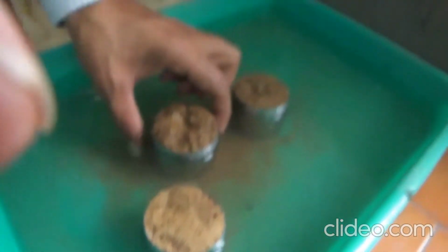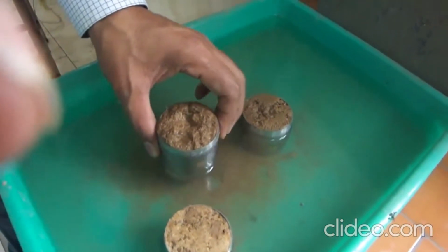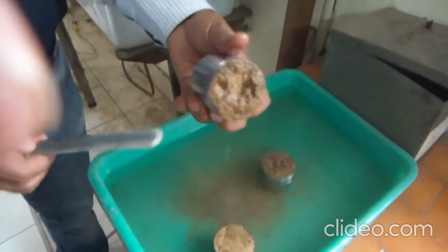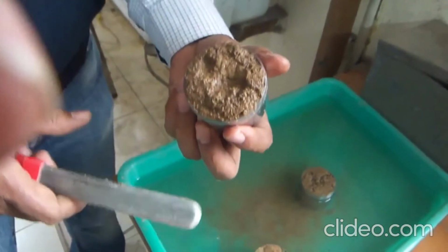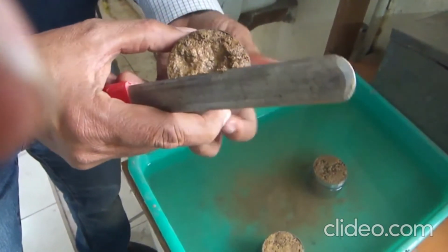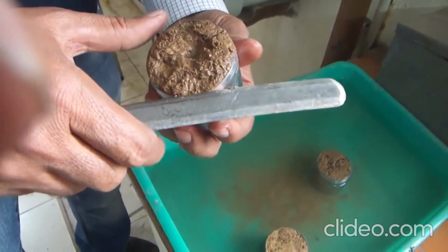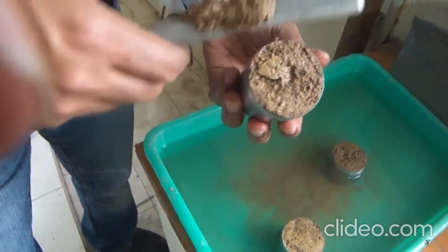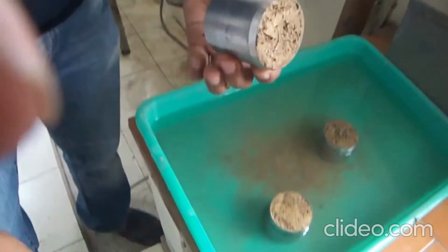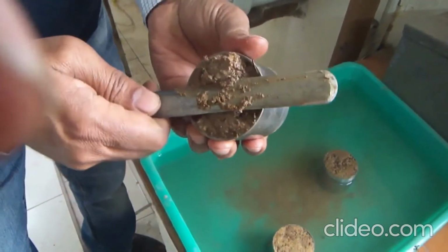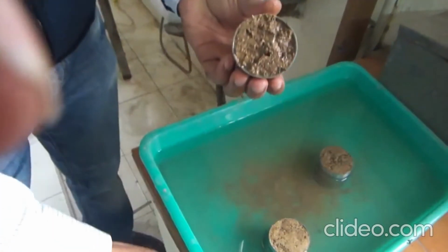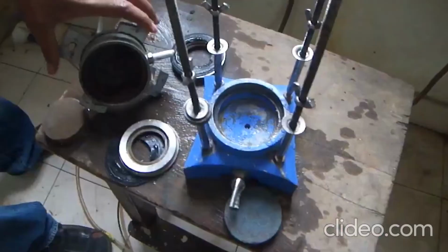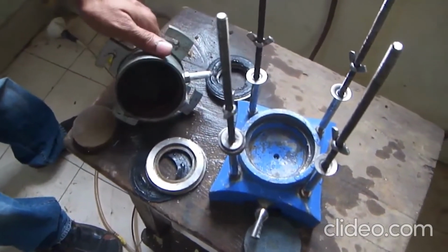So these are two samples we already prepared to show you how the hydraulic conductivity is measured. Now these samples we are taking to find out the hydraulic conductivity of the topsoil surface. We need to first make this level slowly without disturbing the soil. We have taken the sample on both sides, and then it is fitted into the constant head permeameter instrument, to maintain the constant head in this sample.